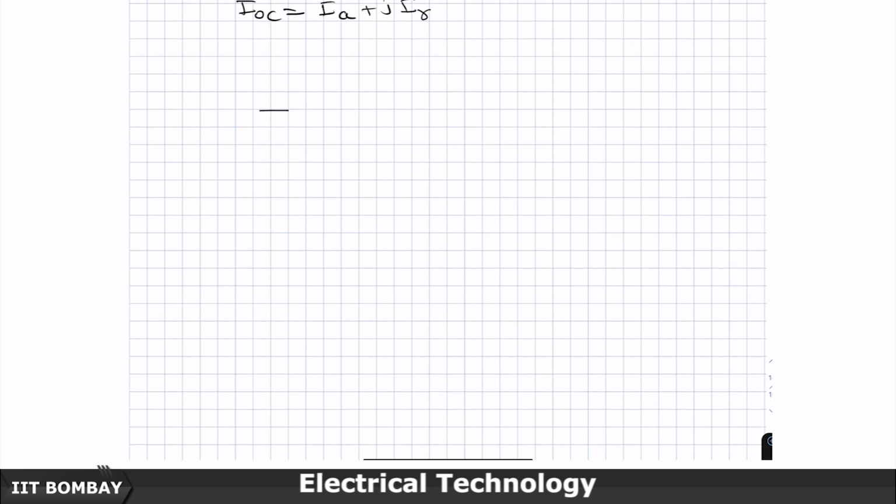So, let me now say that this is the leakage inductance L1 of the primary winding, and then of course, there is a resistance of the primary winding which should anyway come in series with it, because the more the current, the more the IR drop. So, again the same principle is there, that the drop has to be proportional to the current.